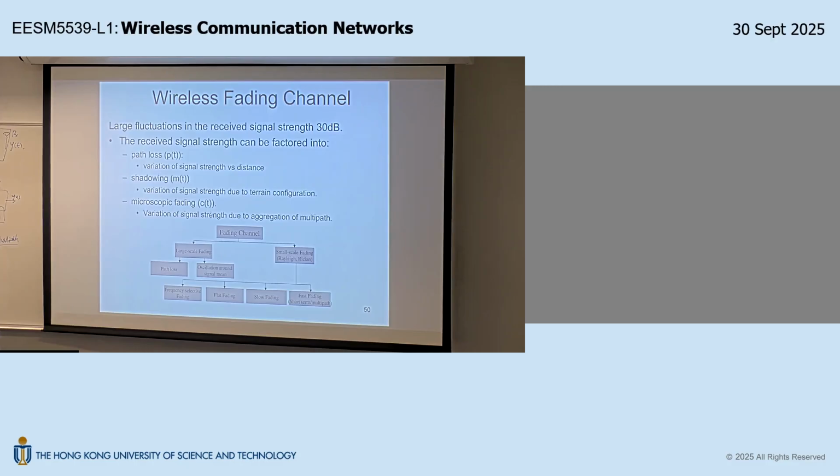This is the same as in a coaxial cable case. In a coaxial cable, I have an impulse response, right? One dimension. So instead of looking at the full description of this impulse response, which is much easier, but still costs some effort, sometimes you go to buy a coaxial cable, you may not be able to get this full impulse response. Instead, they may give you some parameters. For example, the parameter may be bandwidth. It's a number, right? Maybe this coaxial cable has a first order bandwidth of 800 megahertz. So of course, knowing 800 megahertz doesn't give you the specification of this impulse response, right? But it gives you some idea how this impulse response looks like, okay?